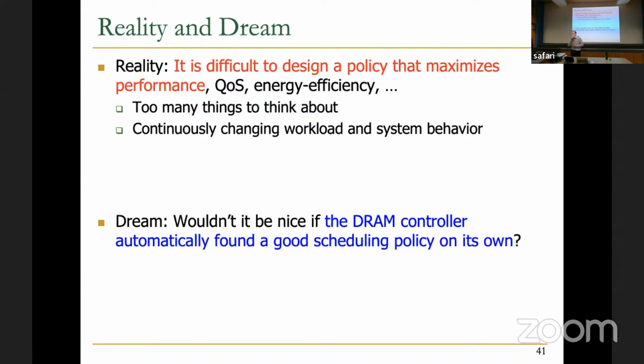I mean, possibly, you could expose things from the memory controller to the operating system, I think, and potentially co-design the system-level memory management policies with the memory controller policies. And there's actually research in that direction, for example, to partition the pages across different memory controllers to solve some of these issues. I think you're getting at things like that. It's possible to do that, yes, and there's research proposals, but that's even harder, basically. That's adding one more dimension to the problem. That's already multi-dimensional, right? So I have not even talked about that, but yes, that's a good question. That basically complicates the problem without solving any of these.